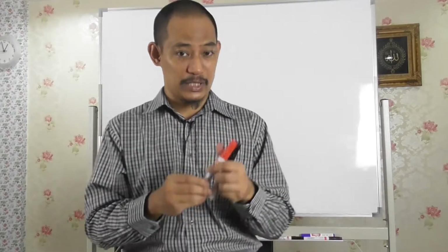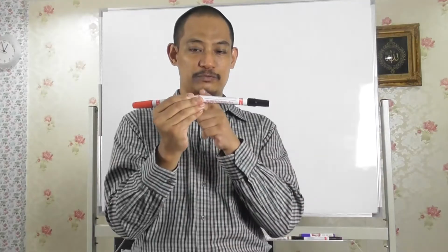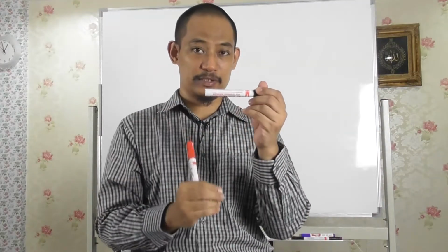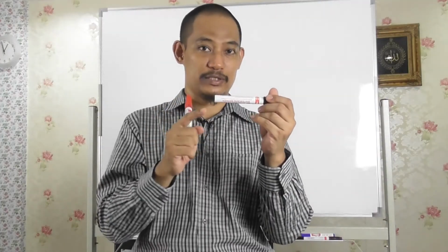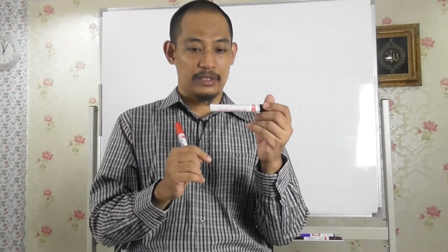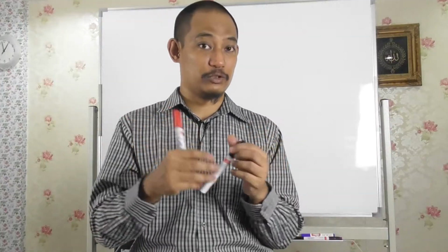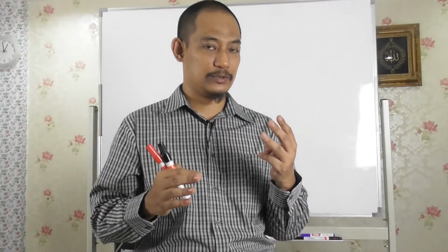So if you have originally a member like this, and we need to find the internal forces at this point, we cut here and then draw the forces, which are the normal, the shear and the moment. This is if we have a 2D problem, and we can solve all of these using the three equations of equilibrium.